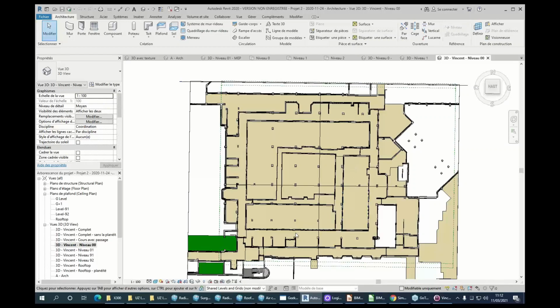We had paper plans, and actually they don't match. The paper plans from the 80s don't match. Obviously, the pillars are about at the same location, but some of them were removed, and we found one additional pillar, which was surprising for us. The partitions have moved a lot, so that was not matching with the plans any longer. So that was provided to the architects, so they could have a correct plan of that floor.